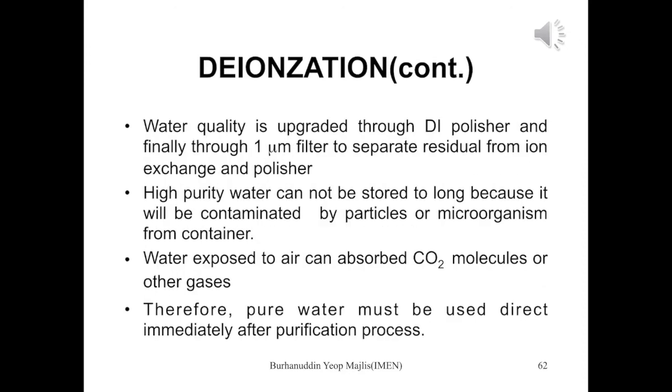Water quality is upgraded through the polisher and finally through a 1 micron filter to separate residue from the ion exchange and polisher. High purity water cannot be stored too long because it will be contaminated by particles or microorganisms from the container.